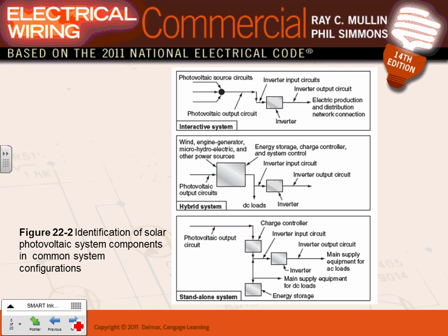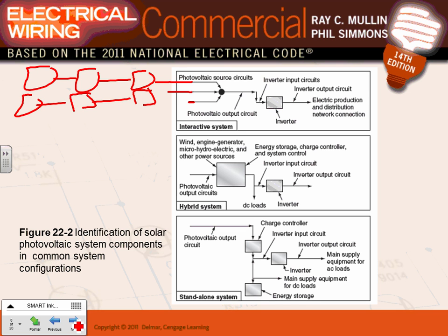Speaking of, when you grab the photovoltaic sources here, this is coming from string 1. You guys remember that one? This is coming from string 2. These are all panels. This is coming from string 3. Each one of them has 5 amps. Out here will be 15 amps, and the voltage that we just used a second ago is 72 volts. You put it through an inverter.